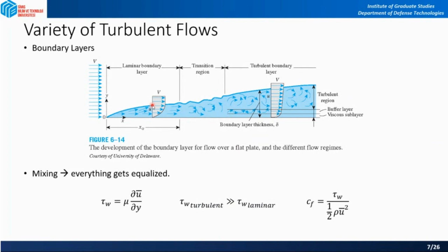And finding the boundary layer velocity profile shape near the wall is challenging. There are different models actually to find this profile. Regarding the drag application in pipe flow, drag for internal flows, we are more interested in kinetic energy losses and in terms of resistance generated inside the pipe, and resistance is due to the wall boundary layer. So they are related to the shear stresses, as you can see in here.